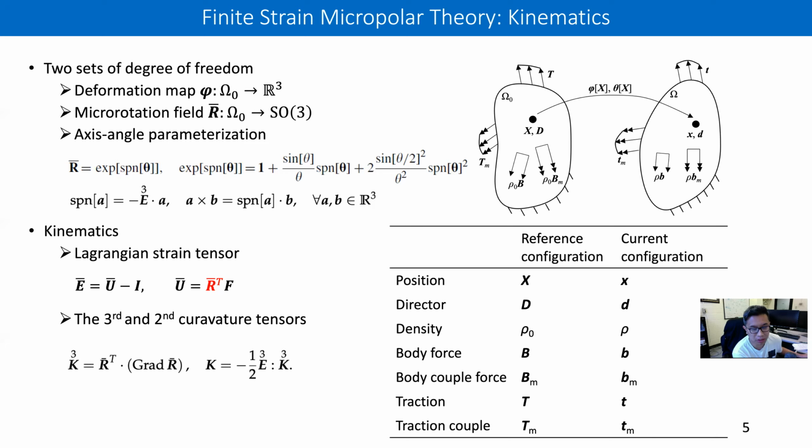which actually corresponds to the Lie algebra of the rotation tensor, and in that Lie algebra, the spin tensor is a skew-symmetric tensor with three unknowns in 3D, and that would be considered a pseudovector that can be added together, or have an evolution law that is actually easier to deal with. We see that in classical continuum mechanics, where the velocity gradient can be split into the rate of deformation and the spin term. That is actually for that very same reason.